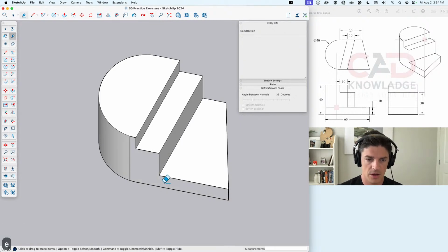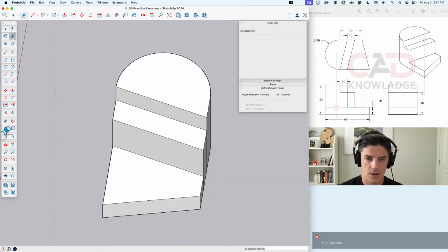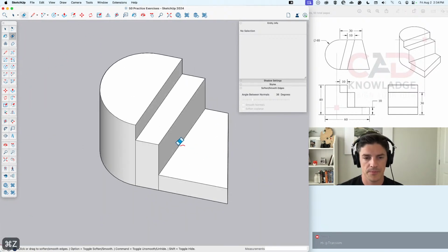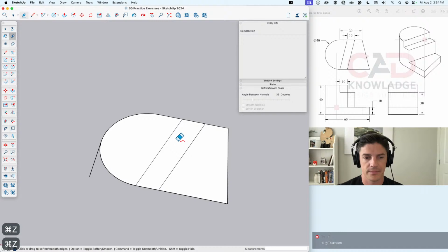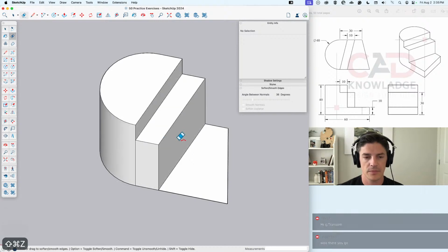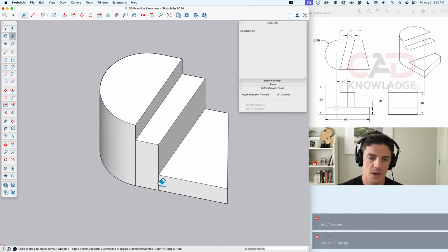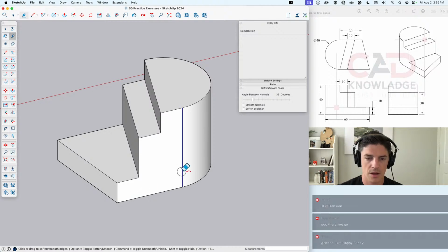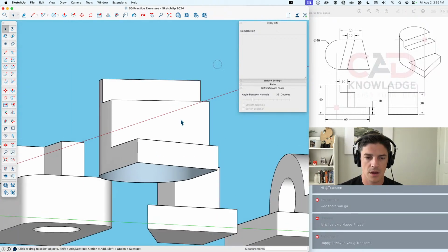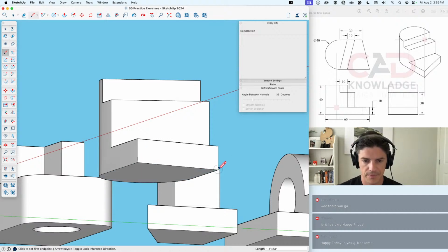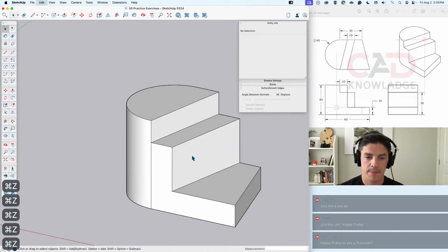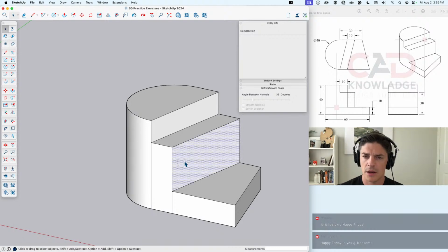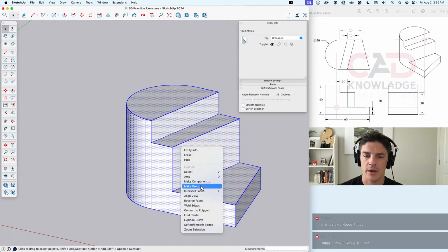Oh, now I wonder if, and you don't have to do this, but if you weld those edges before you pull them up from a flat surface, I wonder if, oh no, you don't really want to weld. I was going to say what you're getting is those line breaks. Maybe you have to because you want it solid, so then you have to go in and clean those up. Yeah. Other options, you can just take the whole thing, make it a group, and can you use the soften edges? Does that do that the same way that the eraser tool does? If you want to make that solid? Yeah, I think so. Or just wait, would this whole thing be solid if I grouped it now?